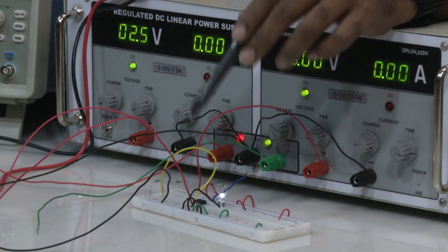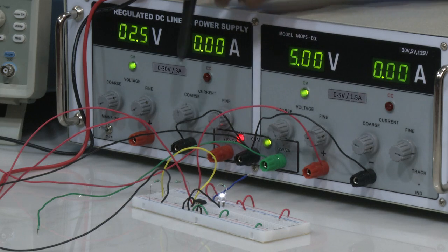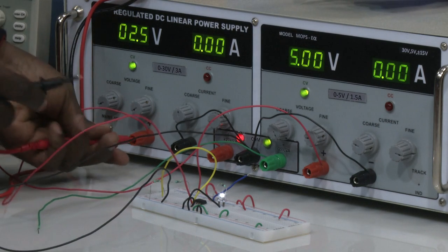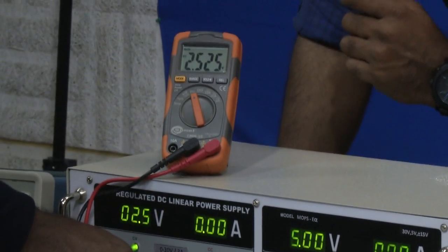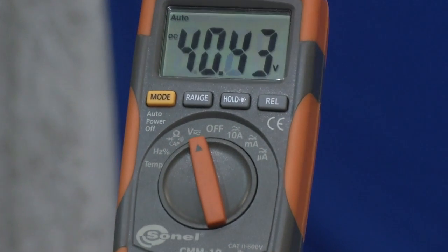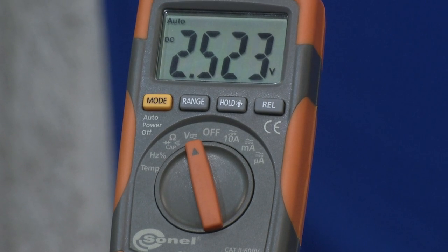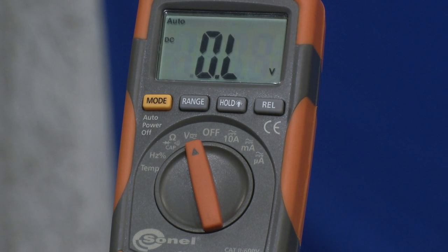This is 2.5, now we have measured the V reference also, right, 2.5. So, this is not exactly 2.5, this is a little bit 2.52 something, right. So, if you want to measure this voltage, you can see what is the input voltage. You can see here on the multimeter it is 2.525, while your input voltage is 2.524 volts. Now, you see the reference voltage across the potential divider is 2.499 or 2.501. That means your V in is greater than 2.5, which is the reference voltage, that is why you can see the LED glowing.